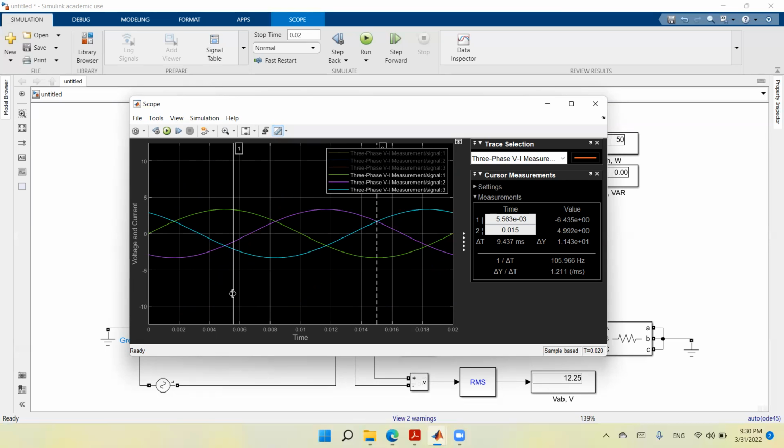Because the sum of the 3-phase currents at any point is equal to 0, this is why we can remove the neutral connection or the 4th wire from the 3-phase system and save one additional wire. So this is the point behind having these phases shifted by 120 degrees.